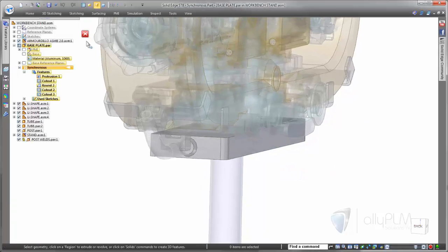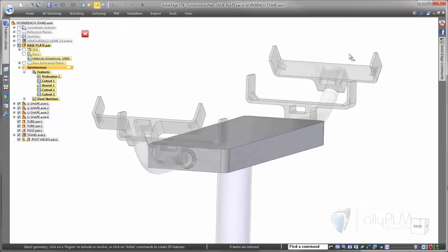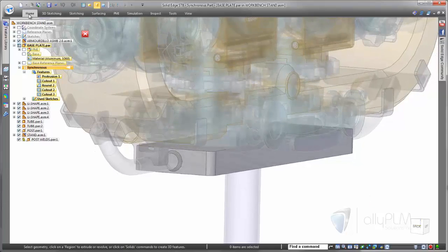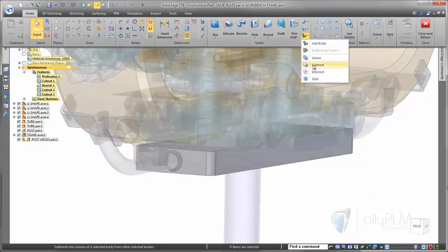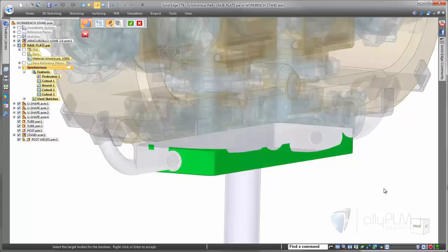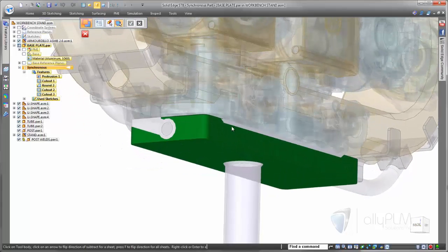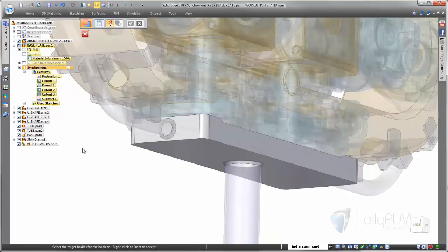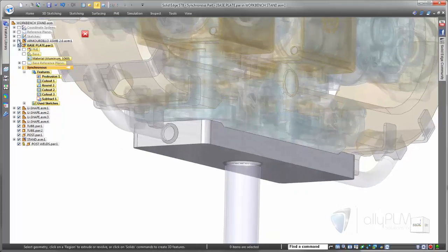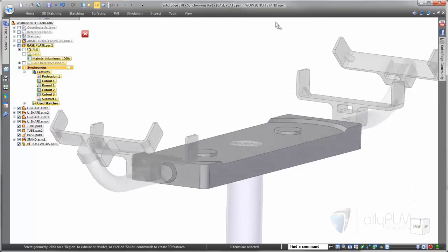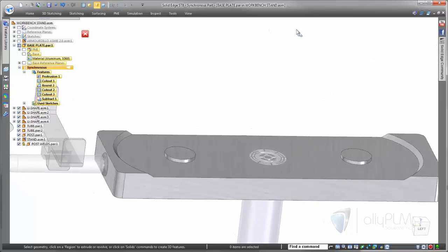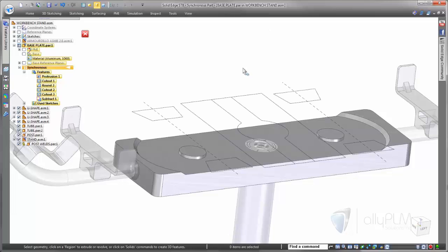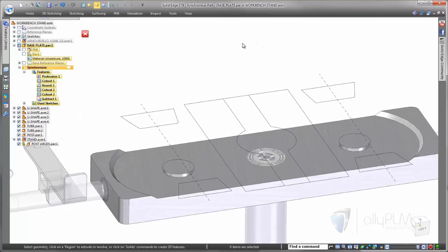When working inside a part environment within an assembly, you still have access to all the tools to make your job more productive. Notice how Pathfinder indicates your active position within the assembly structure. In this example, we want to remove material from the base plate to stabilize the stand. Access to other assembly components is crucial to make this result correct. Notice the result after removing material using the top-level assembly components. This approach takes away the guesswork and becomes very productive.